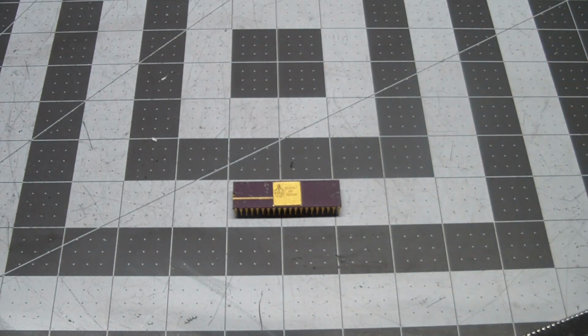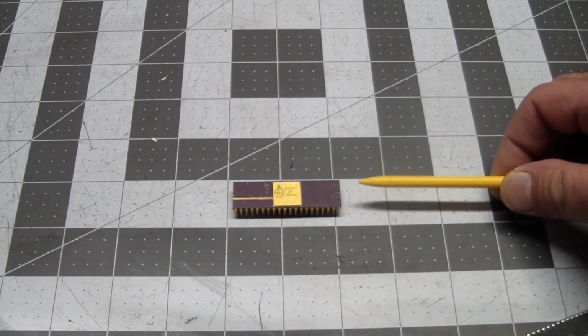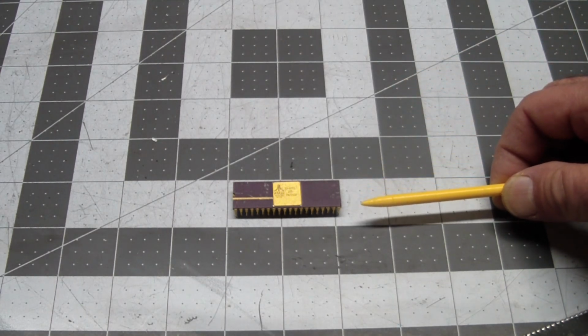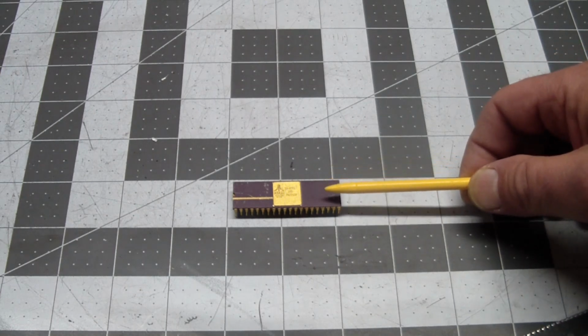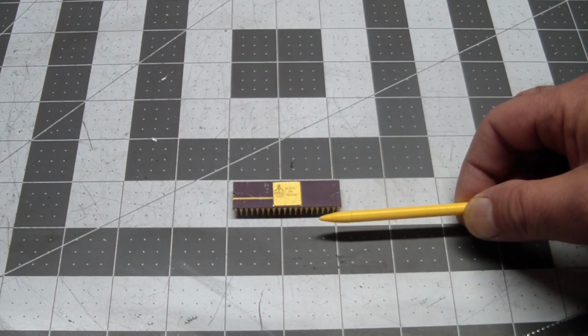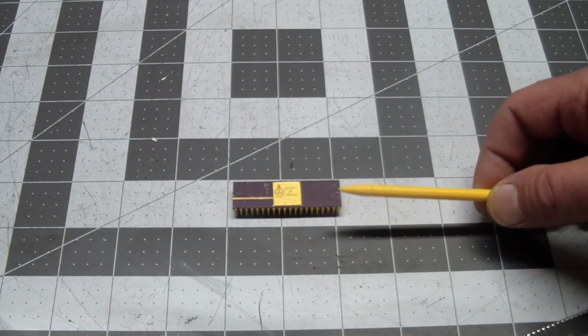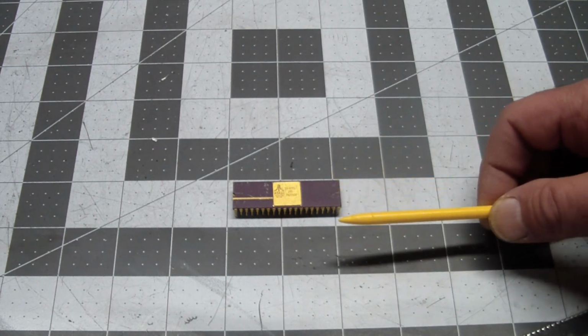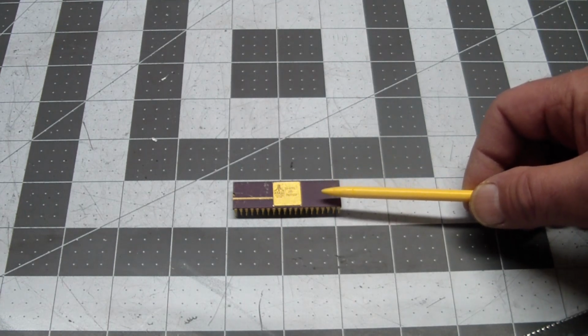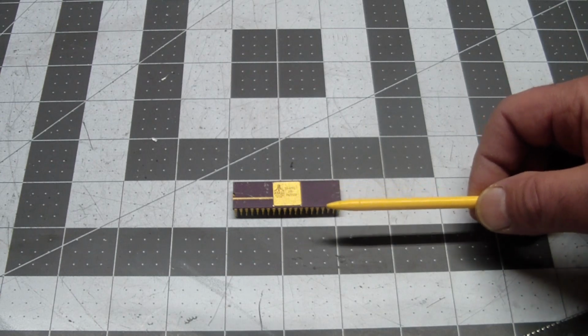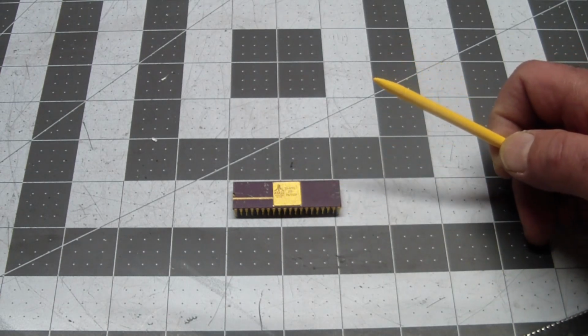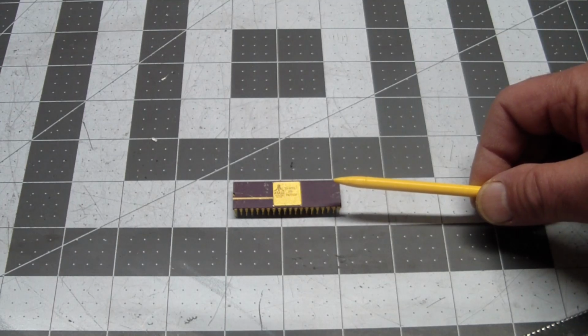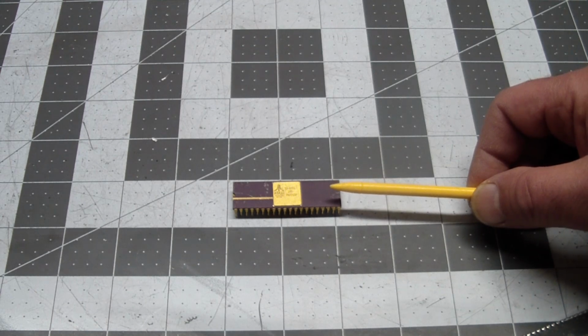6802, and what they did on the 6802 is they gave it internal 128 bytes of memory, and also it no longer requires a biphase clock, but rather you give it a single clock input from a single crystal, and it generates the non-overlapping clock inside. That was the difference between this. So they were more going towards an embedded type processor, even though the 6802 was still a long way off. They also made the 6808, which was essentially a 6802 that wouldn't pass the RAM test on the assembly line.